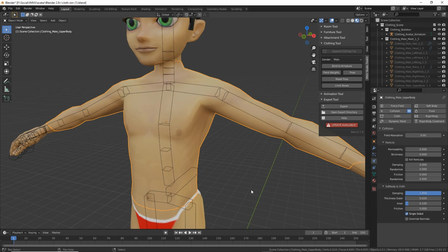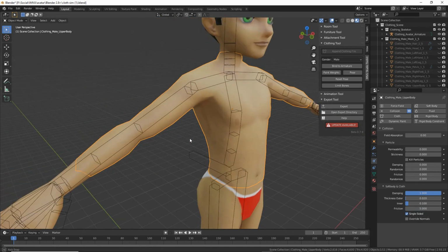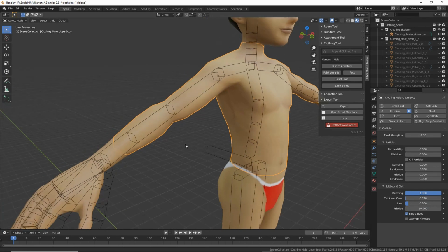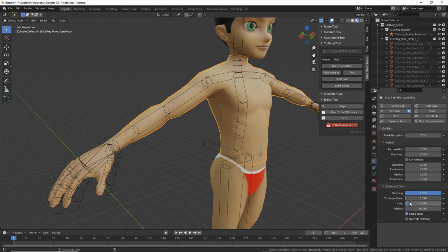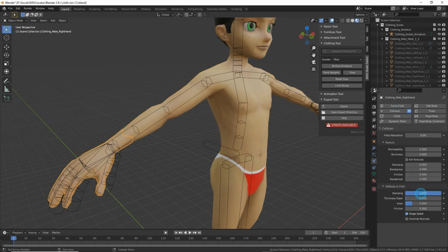And then friction, we can set that also. That determines how resistive the surface is to our simulation. So we can set that to 10. Again, these may vary depending on the avatar that you're using and the mesh density. So those are our basic settings. We need to replicate those to the other parts of the torso. So collision, that's okay. That's 0.1, that's 10.